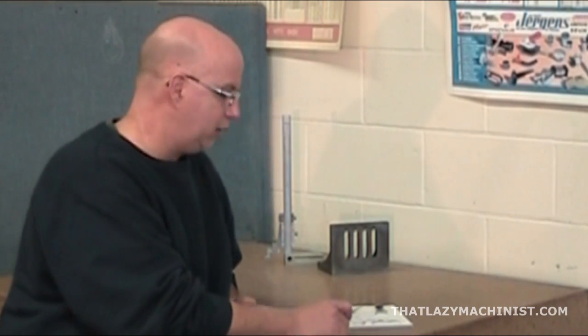These built-up chips are the result of an excessive amount of cutting speed or a worn cutting tool. These types of chips should be avoided at all costs. If you persist with the cutting action that produces this type of chip, you'll most certainly melt the tip of your tool. You may also notice that when you produce built-up chips, the surface finish of your part is often grabby and dull, a little bit like Velcro.